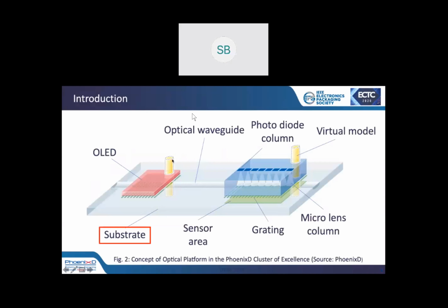The manufacturing of the grating structures can be seen in this slide. The grating structures are created using electron beam lithography and the lift-off or IBE process. The gratings were produced on top of the waveguide structure, on the electroplated waveguide structure.